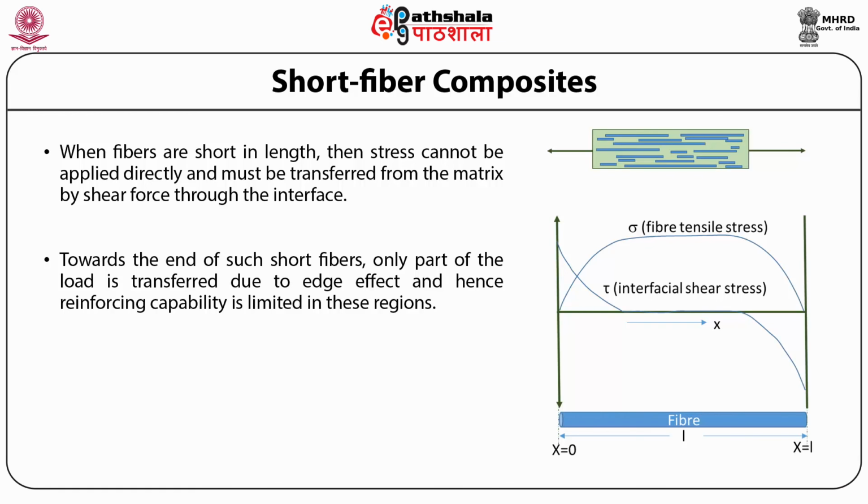This implies that only the middle part of the fiber where the load is saturated is effective in reinforcing the matrix as shown in this figure. The below figure shows the variation of the fiber tensile stress and interface shear stress along the length of the fiber.